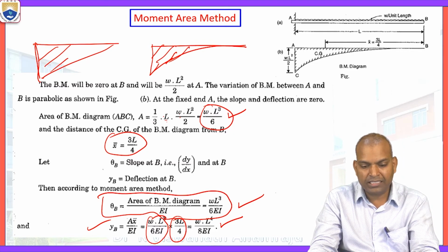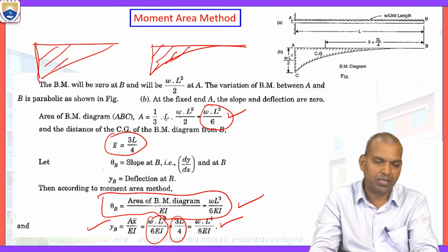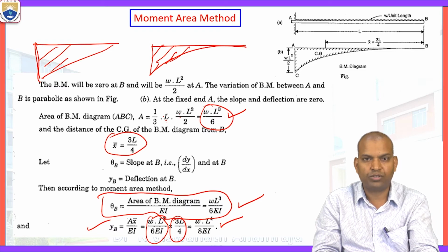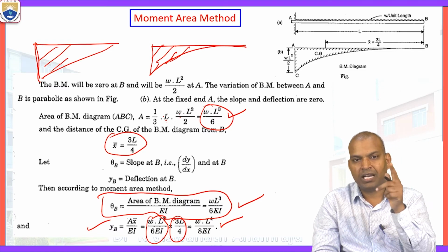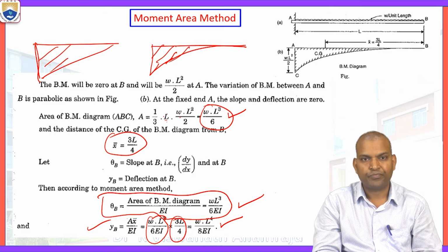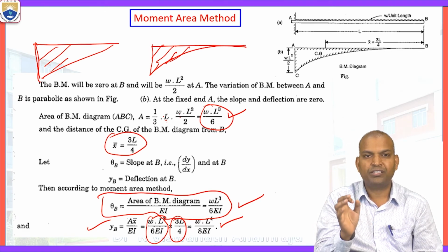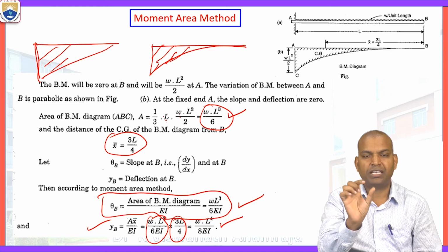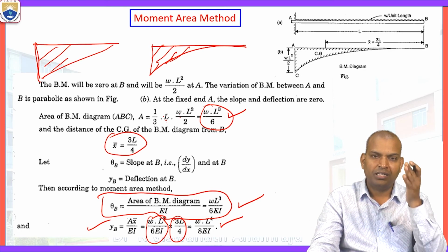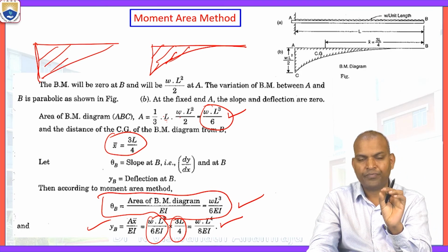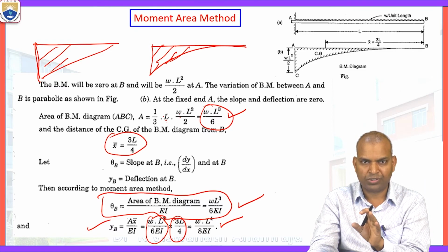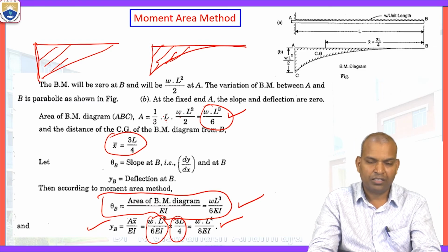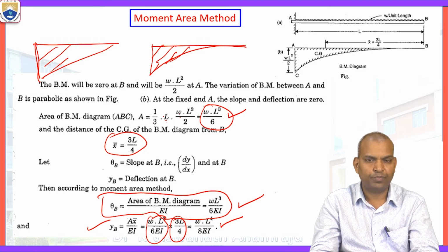So my understanding here, to find out the slope and deflections of various beams at various points, loads and various supports, this much difficulty is not there in the case of Macaulay's method. In Macaulay's method, it is very simple. If we find out the bending moment equation, and apply the boundary conditions for every problem, considering the supports, it's so simple.